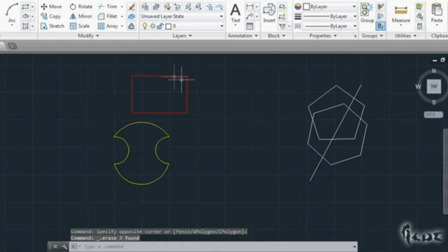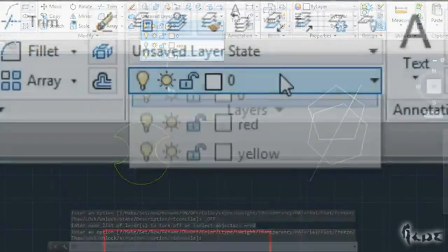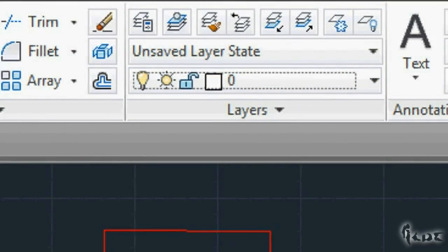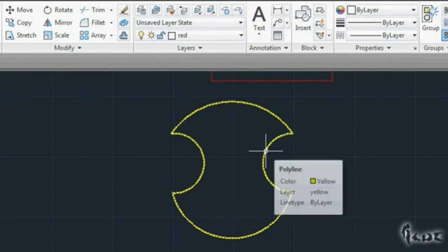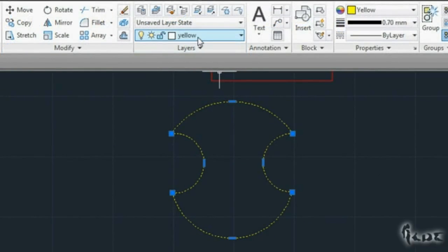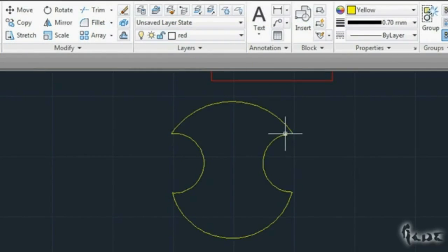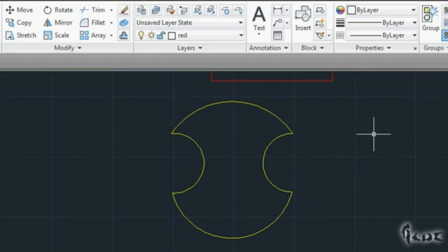You can see this effect also in the third space in the Layers section, next to the colored small square. By clicking on it, you can further check the full list of layers you actually have. And 01 is the one you have by default. In case you want to add new objects to your newest layer, just select them and click on the slot before. Then choose in the list the layer with the name of the newest one. In this case, you won't have any extra copy, since you are just moving an object between two layers.